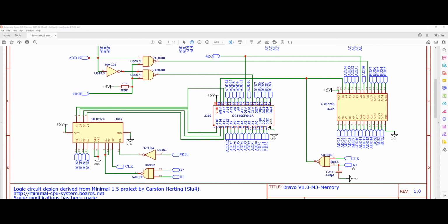However, if you have noticed, we have a capacitor here, and that capacitor basically enables us to have a specific timing for that RAM in signal to be high, meaning that these memory chips require a specific timing for the write operation, meaning that you could only have that signal high for a specific amount of time in order for the chip to do the write operation.